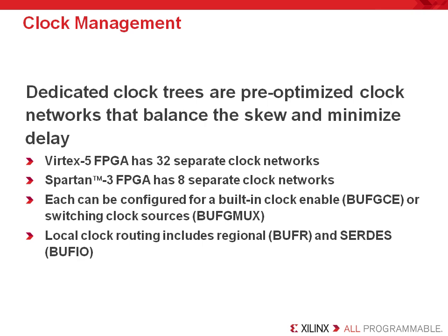The BUFGMUX allows designers to actively switch between two distributed clock signals driving a circuit. So for a while I could drive one, and then we could switch to the other. As I mentioned earlier, there are local clock routing resources for low fan-out clocks and SerDes clock signals. These resources need the BUFR and the BUFIO primitives respectively.